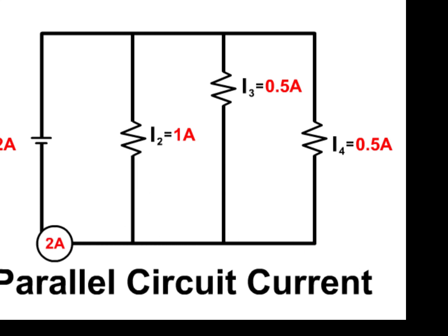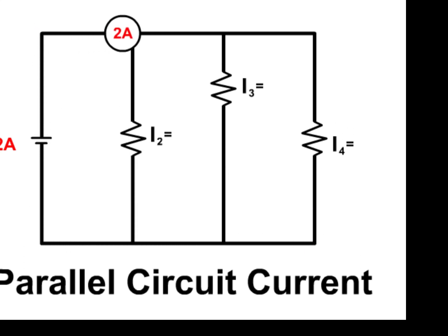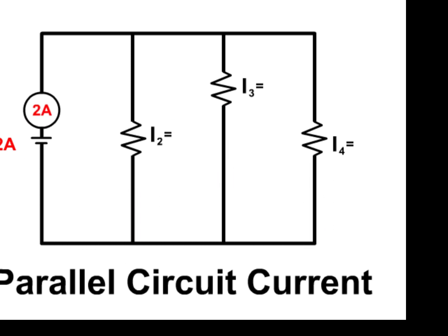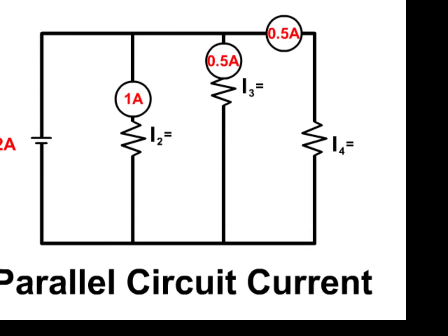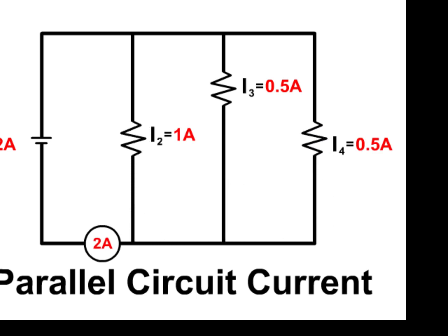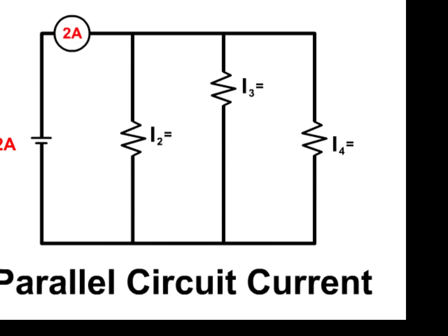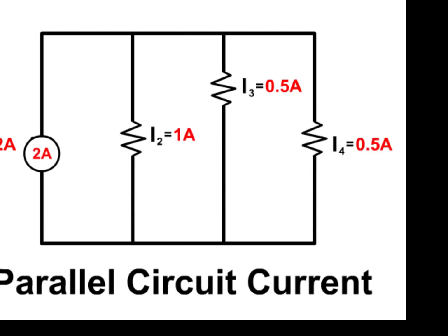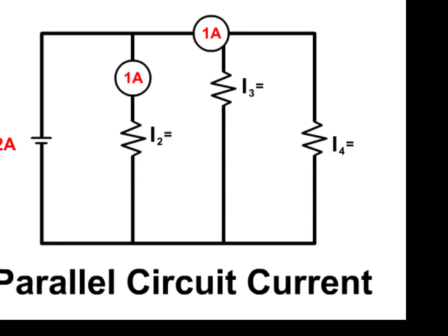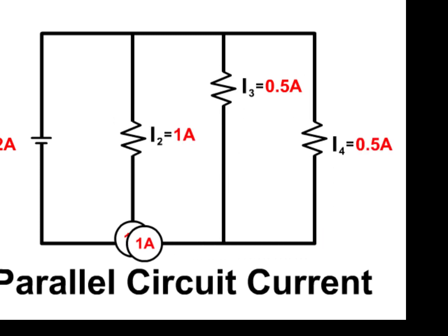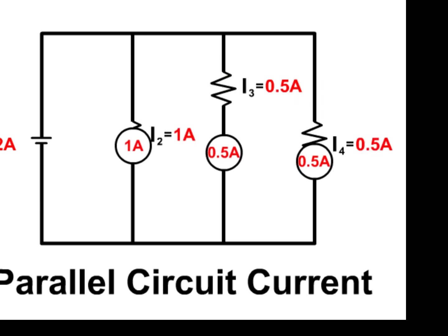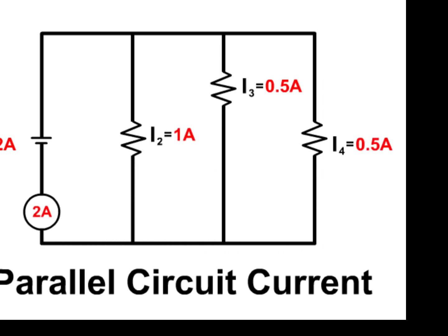Total resistance. The total resistance of a parallel circuit is always less than the resistance of the lowest value resistor or branch. In the circuit, each time another element is connected in parallel, there is less opposition to the flow of current through the entire circuit.